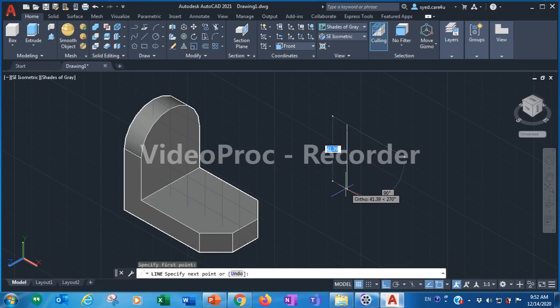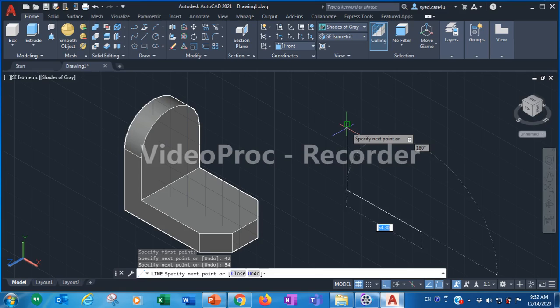Start from here, down 42, press enter, towards right like this. How much? 54. 54, then press enter, then simply go to the starting point or the end point, click here, then press escape. Now we have constructed this triangle, which is a 2D one.